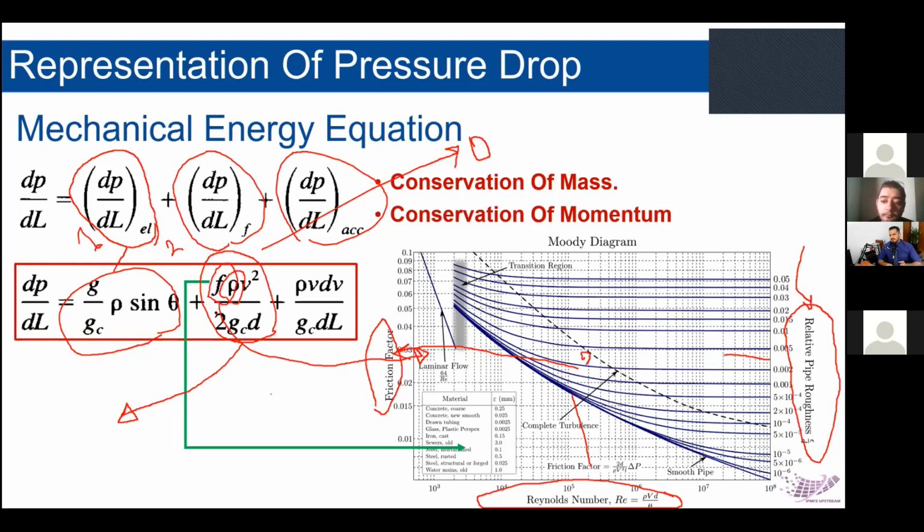There is another method you can do, which is known as the two-gauge method. You should have a sufficiently long pipeline for the injector well. It should have two gauges. Whenever you are injecting at a specific pressure, you need to monitor these two gauges and get the readings. You can plug them into this equation, and it gives you the flow rate.